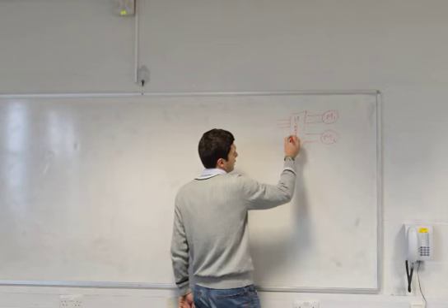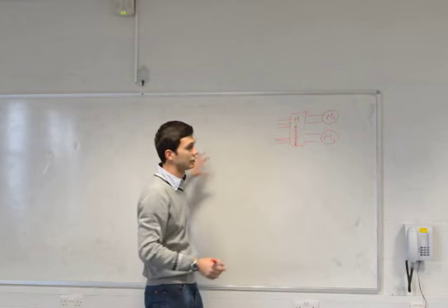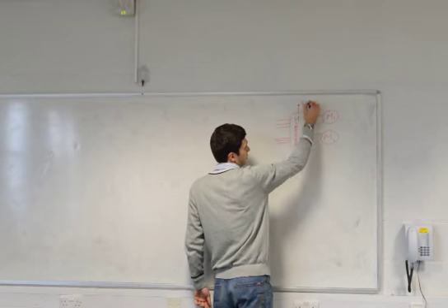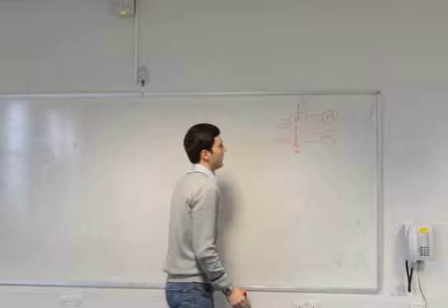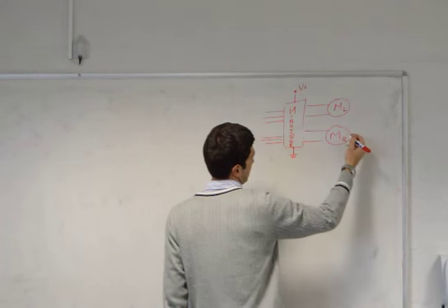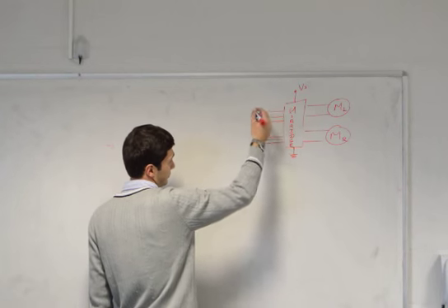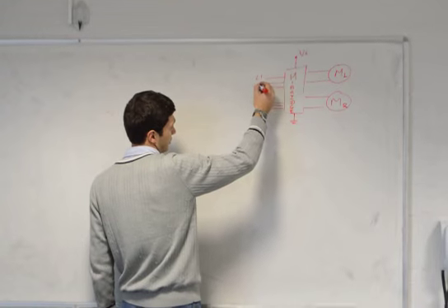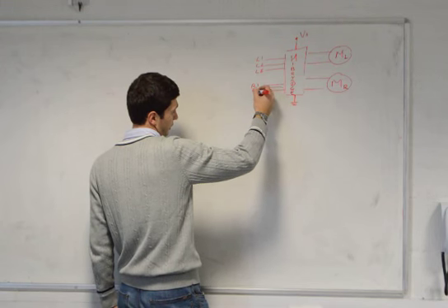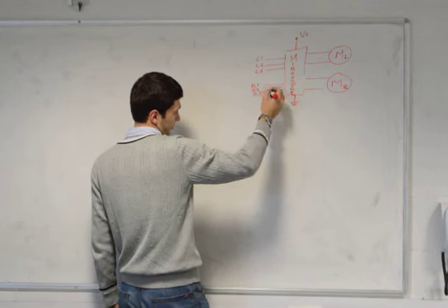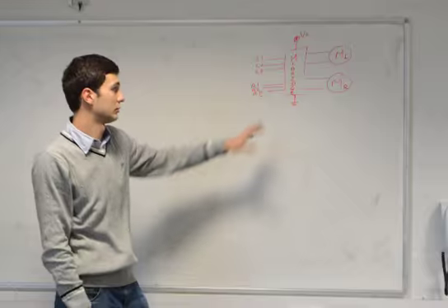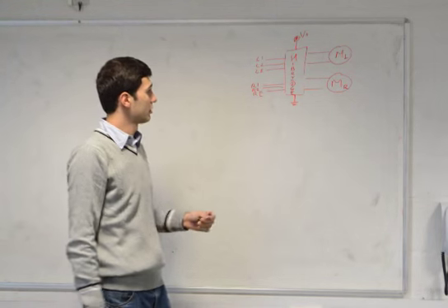Now let's name these contacts, so later on we can connect this to the other part. We have the supply voltage and the ground. Let's run left and right, so it's easier to read. We will have motor left 1, left 2, left enable, and right 1, right 2, right enable. Okay, so this part is done. We have our voltage for the H bridge, and now let's go to the other parts.